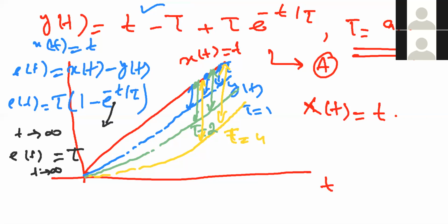In conclusion, we can use the unit step function for the transient response analysis as well as the steady state response analysis, and we can use the ramp function for the steady state error, or you can say steady state response analysis. If you are interested in finding the steady state error, then you can use the ramp function.